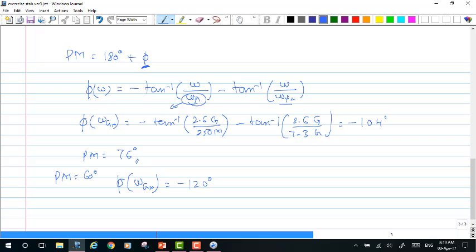But what we want to modify is our Cy capacitance in a way that it also modifies the omega p2 frequency. So what is omega p2 here? The omega p2 is nothing but gm4 divided by Cy. So we need to modify this particular pole. When we modify this pole frequency, we need to end up having minus 120 degrees.